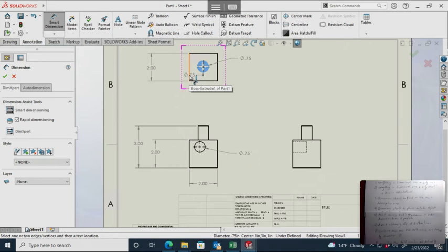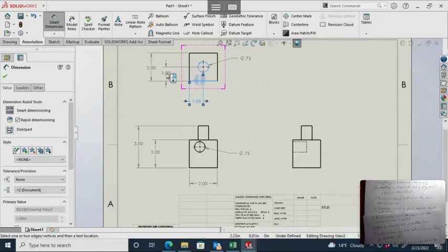And I also need to define, so I'm going to grab that circular arc and this line here. And I'm going to define this length out here. And notice how I'm stacking these one inside the other. I put the largest dimension furthest to the outside, and I'm adding smaller dimensions inside. And I'll do something pretty similar down here.